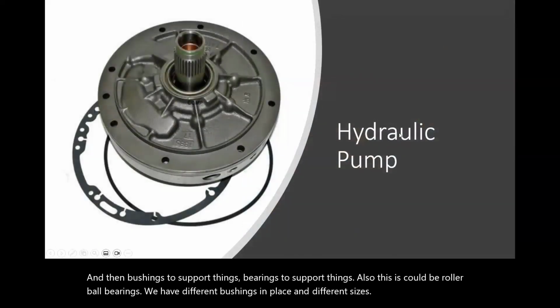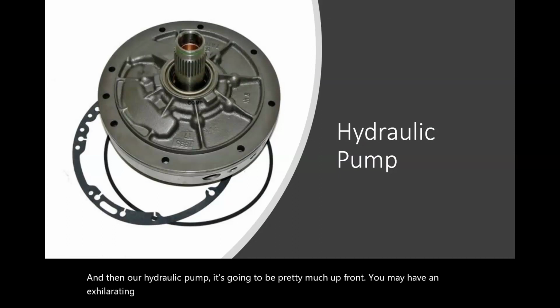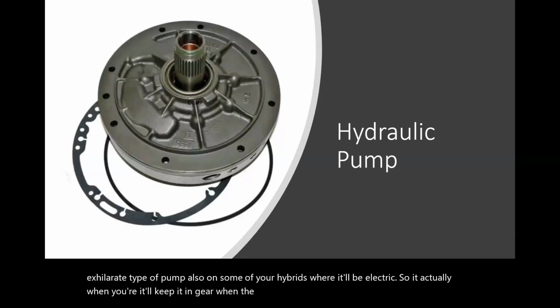And then our hydraulic pump is going to be pretty much up front. You may have an auxiliary type of pump also on some of your hybrids where it'll be electric. So it'll keep it in gear when the engine goes to off mode and you're at a stop sign.